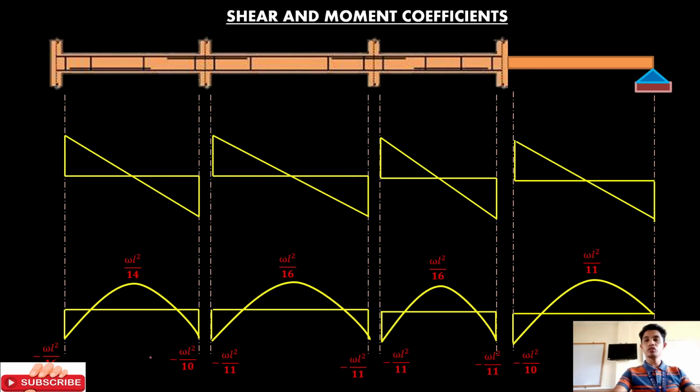So, kapag ito is column, yung negative moment at interior face of the exterior supports, when support is column, WL squared over 16. Kapag spandrel beam, WL squared over 24. So, tandaan nyo na, doon naman tayo sa shear. Yung shear dito, sabi ko nga, dadagdag tayo ng 15%, at saka dito, 1.15 WL over 2, doon din. Then yung mga natira, lahat is WL over 2 na lang. So, mahalagang tandaan dyan is yung L natin is clear span.